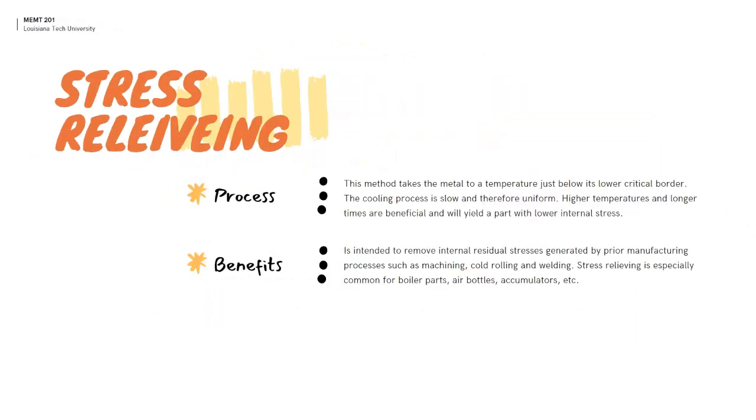Next, we have stress relieving. This process heats the metal up to just below its lower critical temperature and requires a slow cooling process. This lengthier method is beneficial and will yield a part with lower internal stress resulting from plastic deformation, non-uniform cooling, and phase transformations.